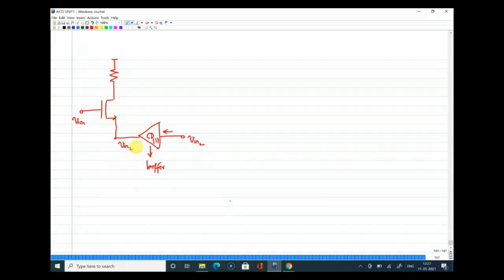Yeah, so I'll wind this up soon. I'll just build the rest of things. So how can I configure a CD amplifier here? What is a CD amplifier? A CD amplifier is whenever you have a MOSFET and I connect it in this form, V in, and take output from here as V out with a constant current here, this is a CD stage.